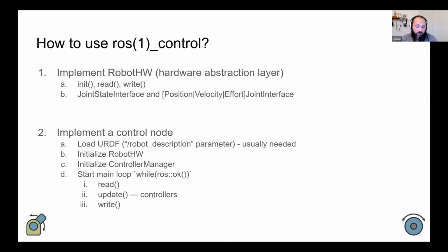Implementing, and so this was the first step, and the second step is that you actually need to write your main application, which is the actual node that you're going to start. This setup is basically always the same. If you're familiar with Dave Coleman's ROS control boilerplate, that is one package that basically does this, because Dave was bored of always re-implementing the same thing, and I bet a lot of people were. So I guess there are a lot of unnamed, uncredited ROS control boilerplate packages out there that basically all look the same.